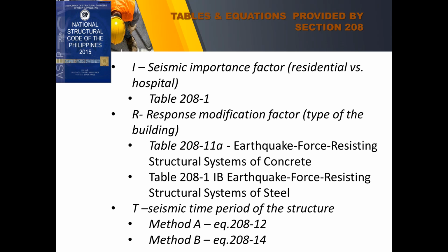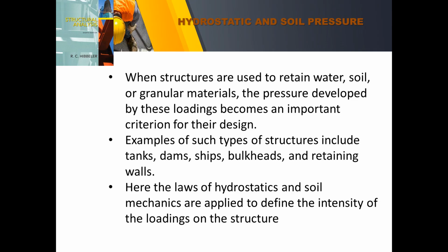And the importance factor could also be found in Table 28-1, together with the response modification factor. Of course, those are the tables. So finally, we have another type of loading, the hydrostatic and soil pressure. Okay, I think you've already encountered this.